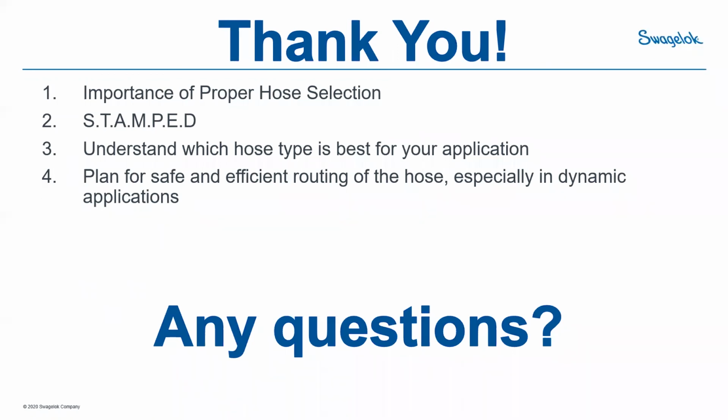Good. And the last question that I have in email is, what do you do when two hose selection parameters are at odds with each other? Yeah, so you have one of those, for my cheat sheet, you have a green dot and a red dot. A lot of times what we tend to do is start with the PTFE core hose, which tends to be a general middle ground that works well in all applications.